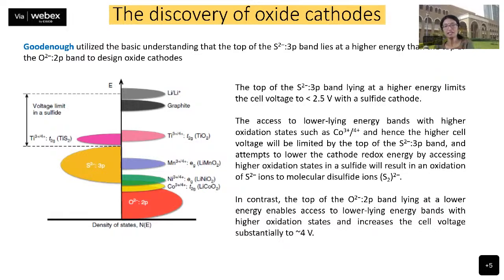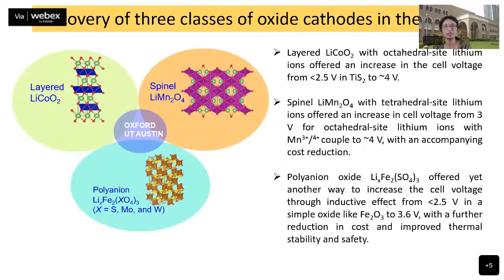So this was basically the idea, and immediately you see, the moment they came to oxides, this is your energy measured against lithium or graphite, you just see how the voltage immediately increased. Where the voltage was around 2.5 volts when you are using TiS2, in this case the voltage moved up to almost 4 volts, and immediately the energy density showed a remarkable improvement.